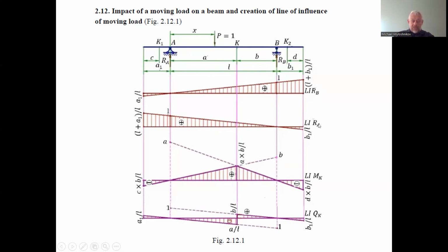One of these two lines of influence is used for the left part of the line of influence of the location of the point of application of the unit force on the shearing force, but with another sign: we have a negative sign here and positive there, with the same magnitudes. If we need the left branch, we consider the balance equation for the left part. If we need the right branch of the line of influence, we consider the balance equation of the right part.